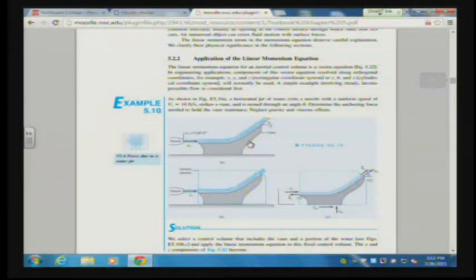And this is basically, the picture that they draw here is a vane where we have water squirting out of a nozzle, and the water is moving along the vane, and the water is exiting or leaving the vane at some angle theta due to the shape of the vane. So they've drawn the control volume around the vane, and you can see that the water enters here and exits here, so that the linear momentum of the water going in is all x directional, but coming out we have a different angle, so we have some x and y stuff.